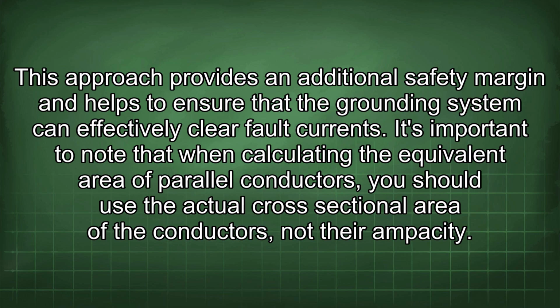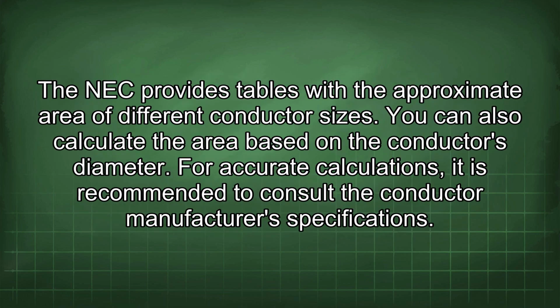It's important to note that when calculating the equivalent area of parallel conductors, you should use the actual cross-sectional area of the conductors, not their ampacity. The NEC provides tables with the approximate area of different conductor sizes. You can also calculate the area based on the conductor's diameter. For accurate calculations, it is recommended to consult the conductor manufacturer specifications.